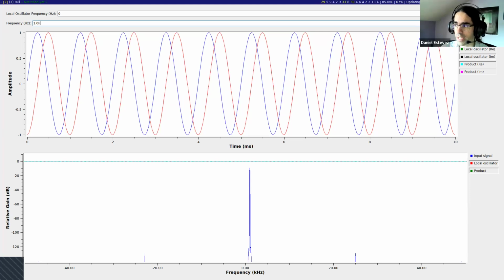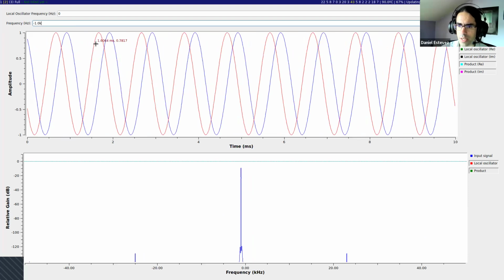So if you see I and Q, or IQ, that's the same as real and imaginary. So I leads Q, that's the way of remembering. When the frequency is positive, I leads Q. When the frequency is negative, it's the other way around, Q leads I.